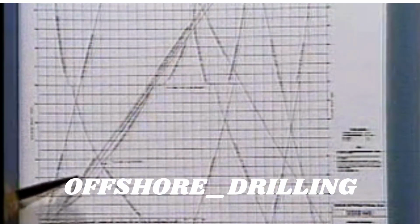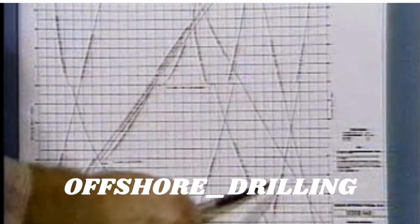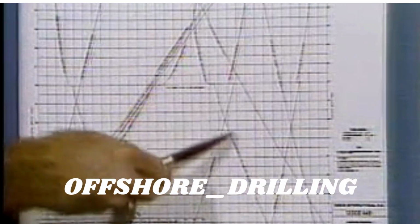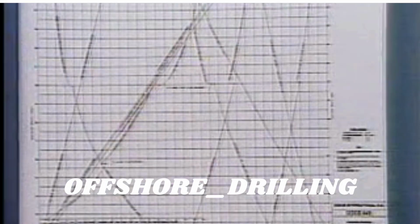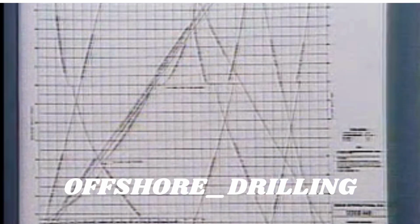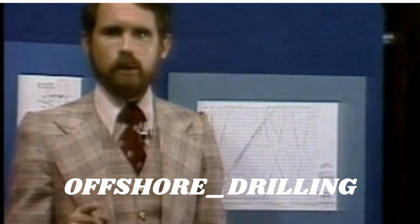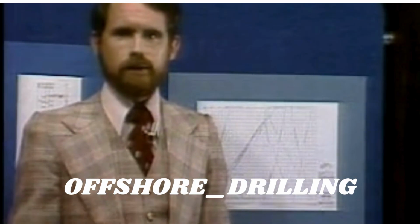displacement in fresh water, salt water, MT1, change in displacement for trim by the stern, longitudinal center of flotation, longitudinal center of buoyancy, height of the transverse metacenter, and some additional information of a design nature. Once we have located the desired curve, we find the point where the applicable draft line intersects it.